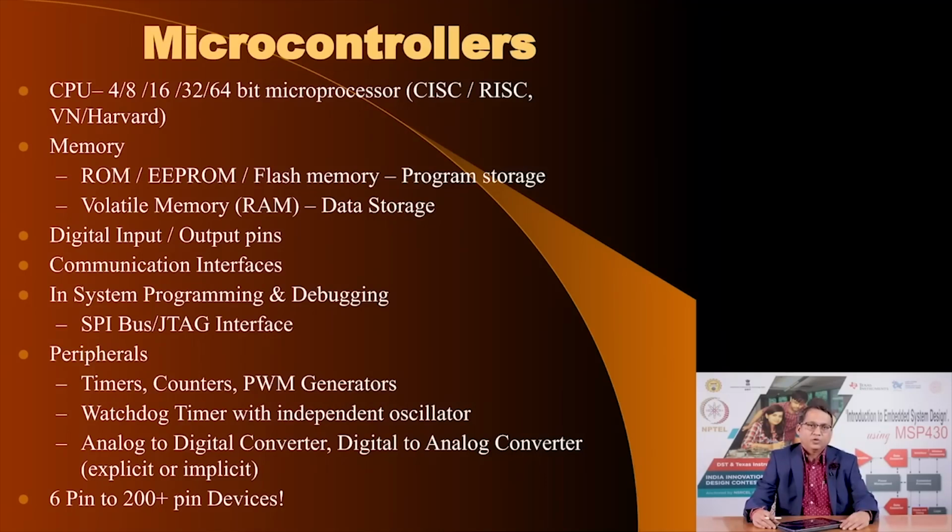We will get into the details of all these things that I am mentioning here once we start talking about the actual microcontroller. But these are the requirements that these memory devices have to perform, and therefore you would require a permanent memory with EEPROM, or it is more common these days to find such permanent memory of the type of flash. And for volatile memory, it is usually SRAM for the data storage.